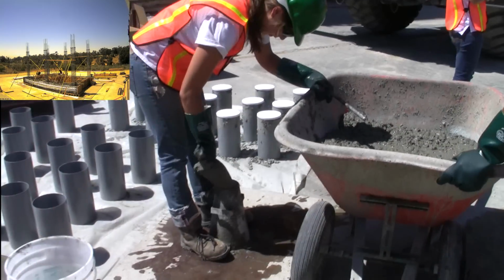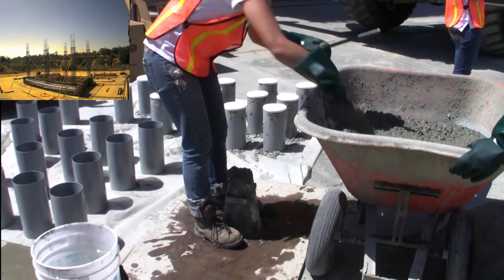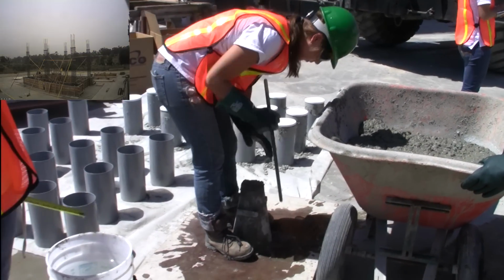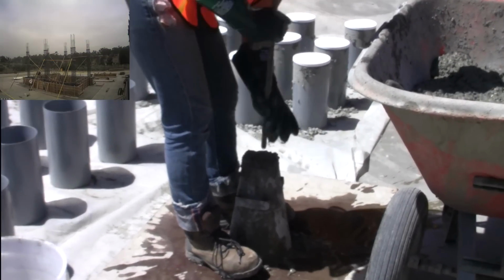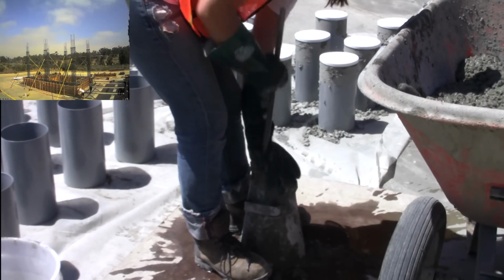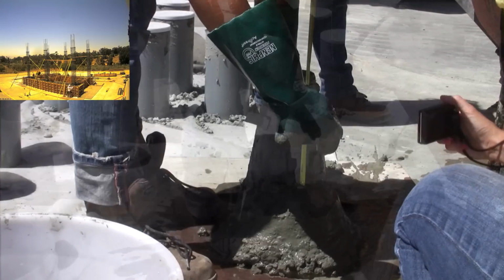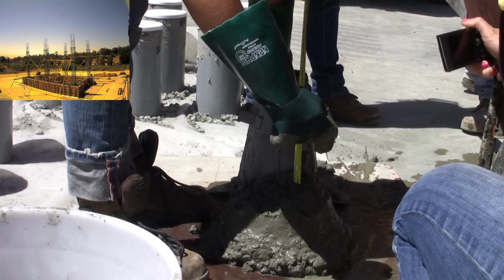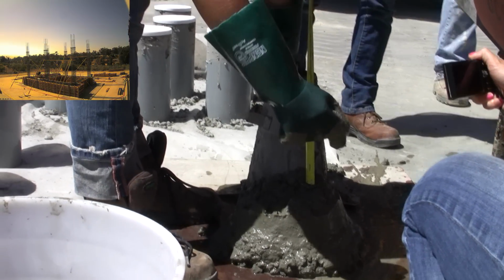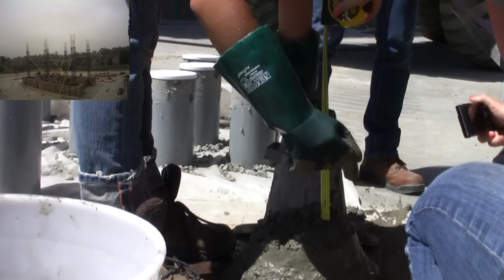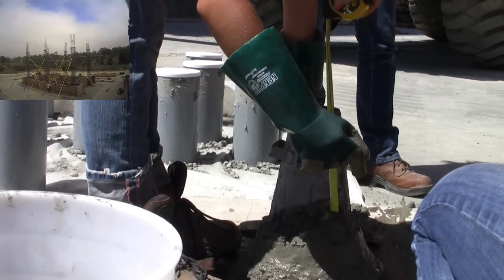Once the rebar cages and formwork are complete, the foundation concrete is poured. Before the concrete is poured, a slump test is conducted. This essentially consists of pouring a sample of the concrete into a small cylinder and then lifting and removing the cylinder. The amount the concrete slumps down provides an indication of the workability of the fresh concrete. Once the desired slump is attained, the concrete is ready to be poured.